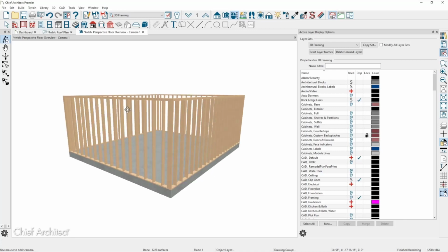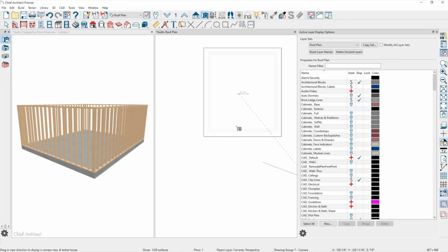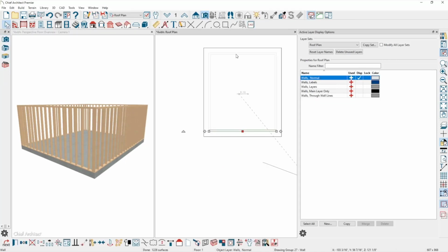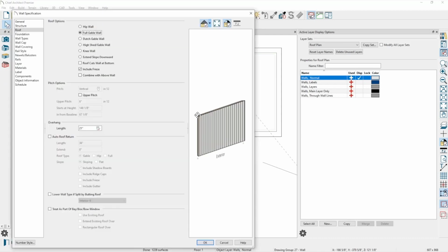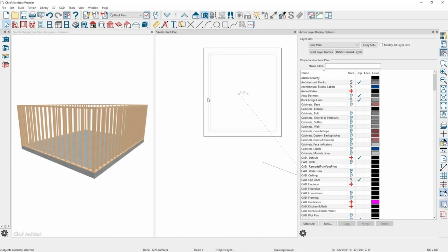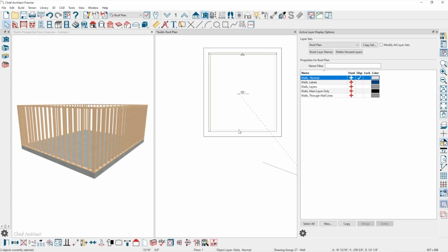Now you can mark that wall as a balloon wall. Have you used that feature? Yeah, and I think somehow that's necessary here because there is no attic. I want the room to go all the way up to the roof. Right. But I have to almost manually dimension each wall to get it to do that. So if I mark these 2 walls as balloon through, that's going to force, in fact, let's make sure we grab all 3 walls and have those balloon up.